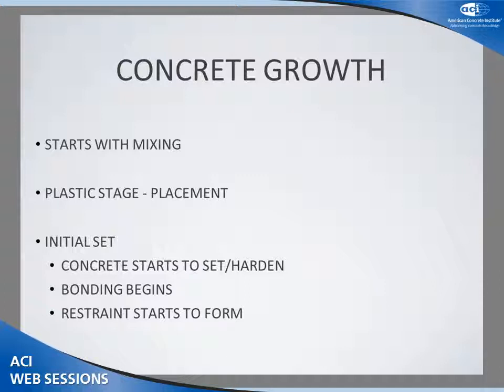In order to eliminate shrinkage cracking, we must develop restrained expansion. If we add a shrinkage-compensating component to an unrestrained concrete test specimen or a construction member, we will get greater expansion during the initial stage of curing. As the concrete hardens, it will grow and be larger than its as-cast volume. More expansion than you would get with conventional concrete.